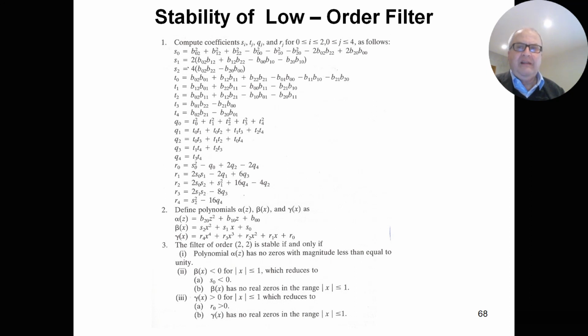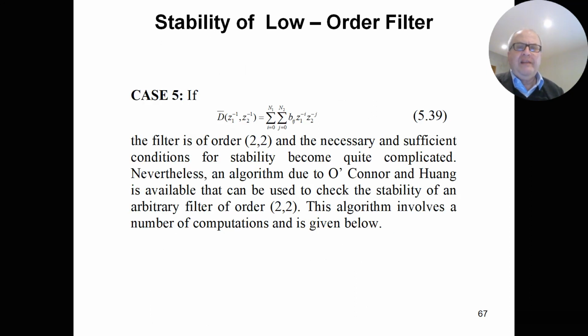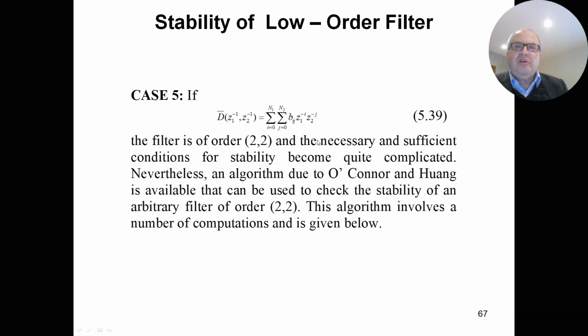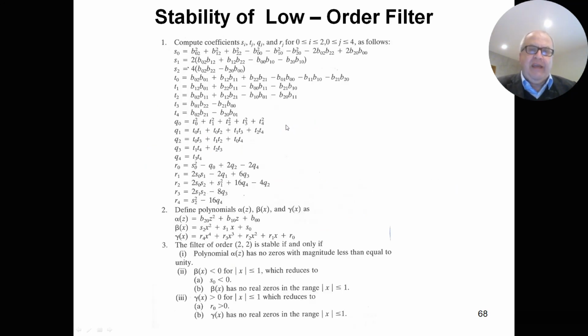So until now, we design complicated two-dimensional filters where the transfer function has as denominator products of factors of first degree. So in the denominator, in the most complicated case, you must have factors like this, not factors like this with n1 and n2 equal to 2, because the optimization problem is extremely difficult and complicated.